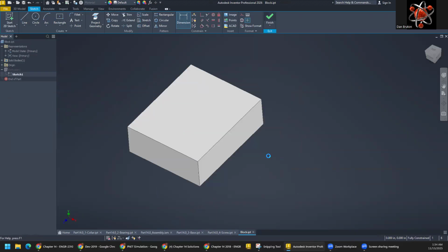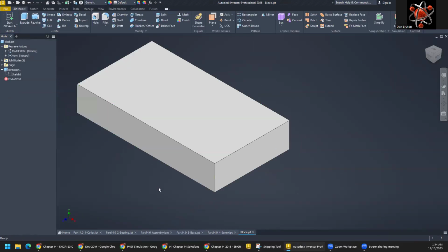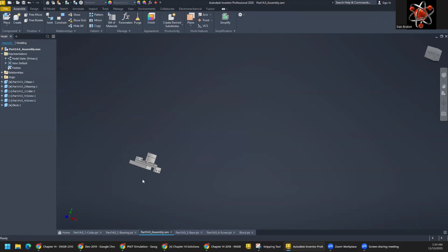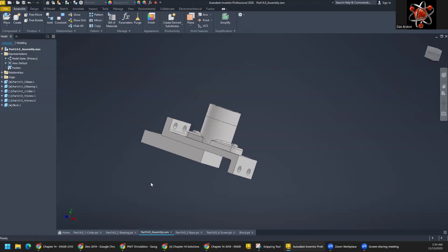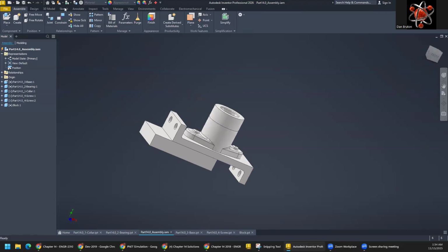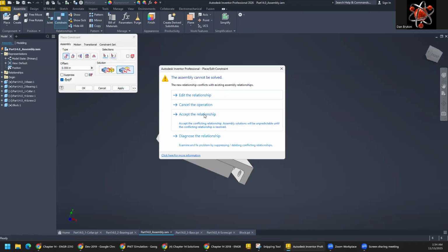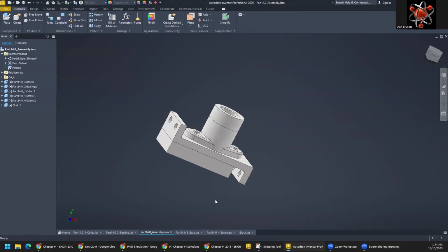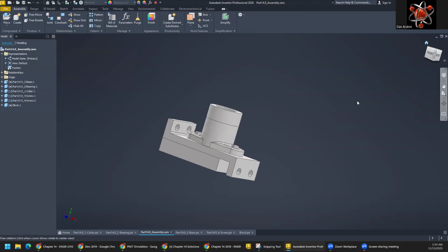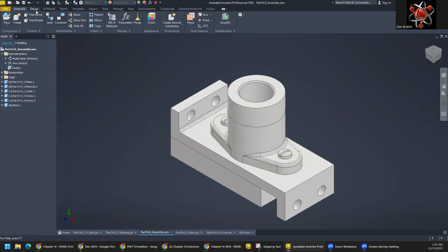Then click OK. We'll probably have trouble with that symmetry when we go back over here to the assembly, but let's just see what happens. Yeah, it had a little trouble with the symmetry because it expanded in both directions. So we just make these two not mates, but flush. Okay. And it says we've already really done that before. It's just resetting. We have finished our parts, and so now we make our final thing, and that's going to be